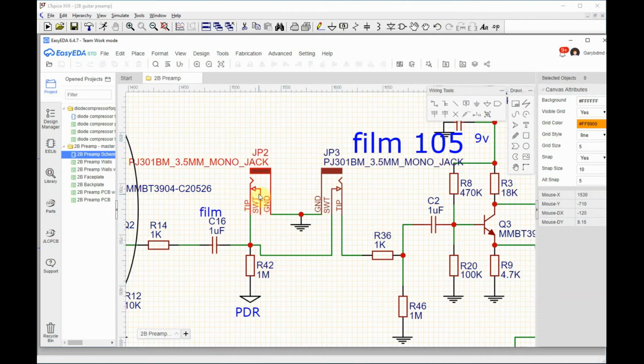You have to think about the input impedance coming back in. You got to know sort of what impedance you're going out to, of course. And the reason that's important is you have an output source impedance right here. And so you got to make sure that's low enough. I have mine at like 1K, so that's good enough, but it's not good enough for like low impedance applications. So you might need something a little different.